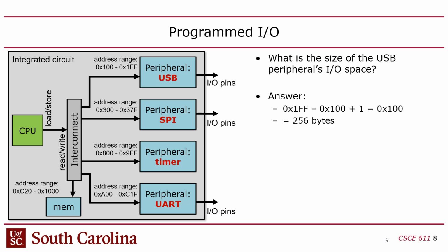Okay, so the programmed I/O is a parallel interface that typically goes through some kind of on-chip interconnect. And so when you do a load or a store, and again, when I say load or store, that's from the assembly level perspective. From your C perspective, you're using those intrinsics, or dereferences. Makes sense?